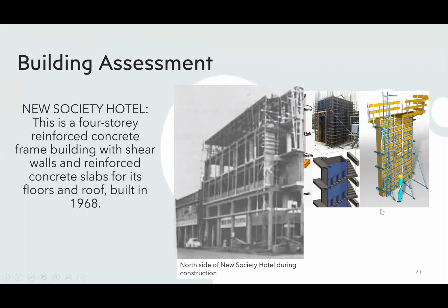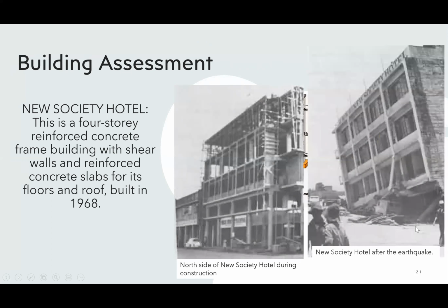A column on the southeast corner of the second floor suffered torsional failure, most likely due to torsional irregularities, meaning there was eccentricity creating some distance between the center of rigidity and the resultant lateral forces at that level. In addition, adjacent walls in the location of the building also suffered out-of-plane shearing, and the northwest corner of the second floor fell into the streets. Earthquake damage to structural elements usually results in the degradation of the mechanical properties of the concrete.